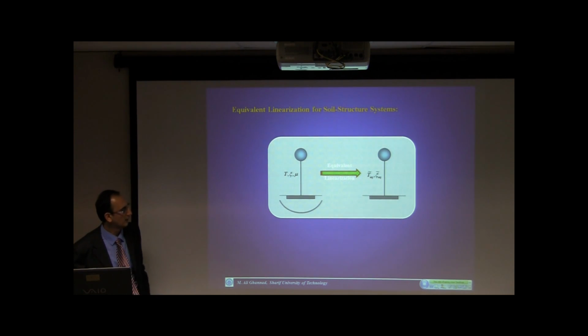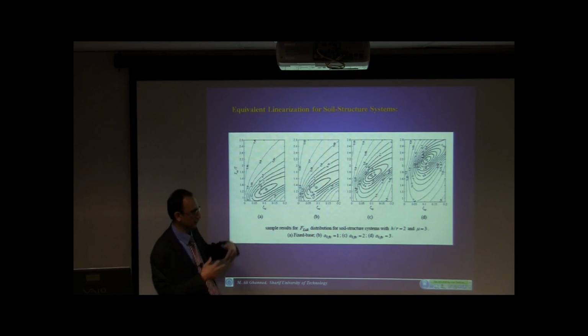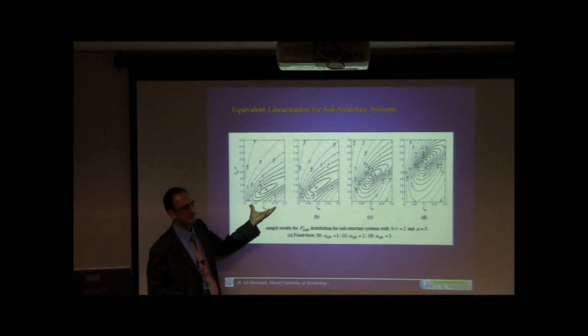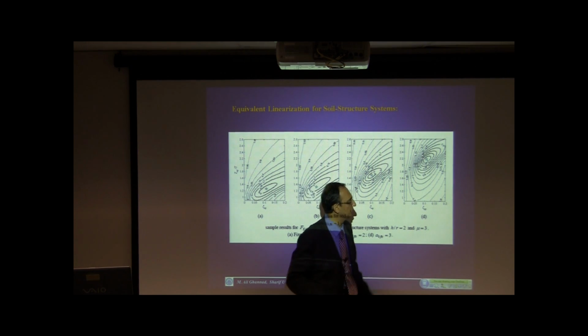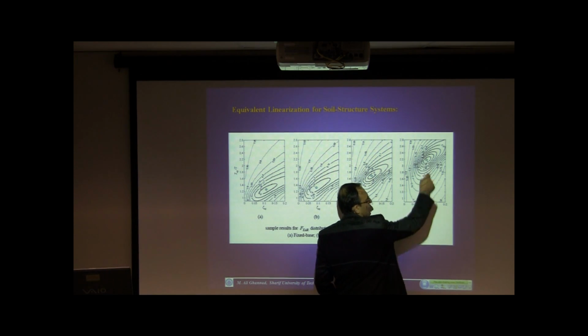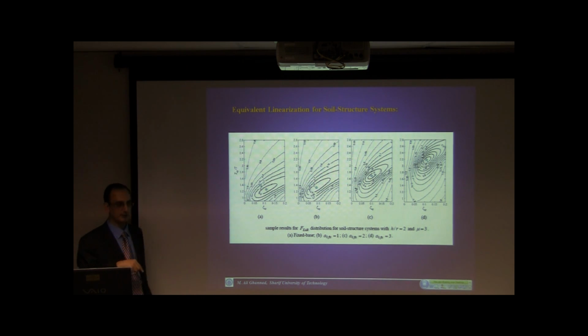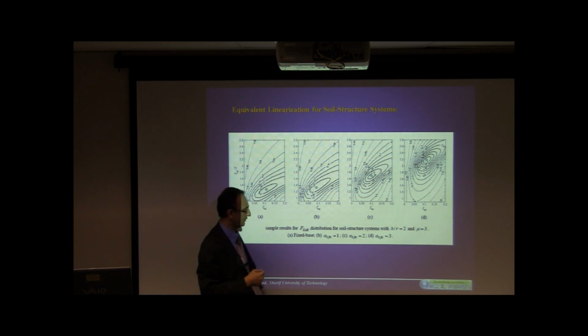Now we're back to our own problem. These are the graphs that we generated for the soil structure system, just one sample. It's very similar. This is for the fixed base, which can be compared with the results of Ivan. We tried to use the same database as he did. And it goes for different soil structure systems. The shape of the contours is going to change. The sensitivity of the results increases with the soil structure interaction. But as we'll show later, the reliability of the results for the soil structure interaction increases with increasing parameter A0.